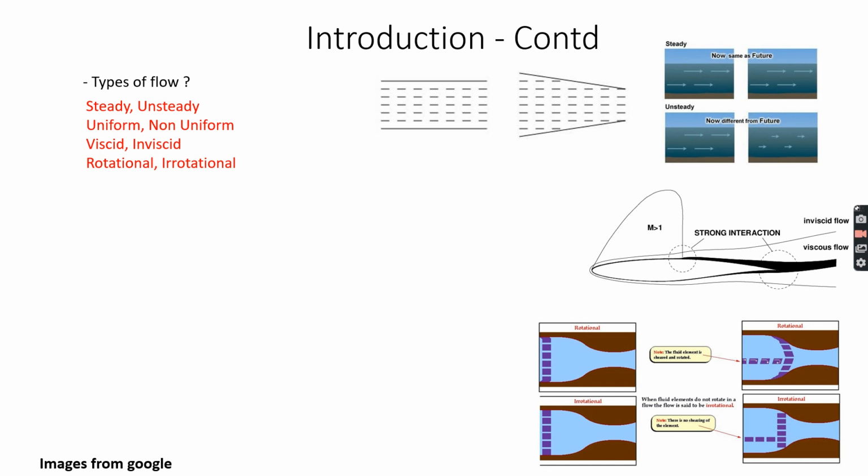If you want to look more into this, there is something called the Q criterion, which you can look up on the internet, where the positive part of the Q criterion gives the flow to be rotational, and the negative part of the Q criterion gives the flow to be sheared. And if the Q criterion is zero, then there is no shear and no rotation in the fluid. So this is one of the key aspects which the community uses to look at whether the flow is more irrotational or more sheared, or the buildup of vortices in the rotational part, and so on.